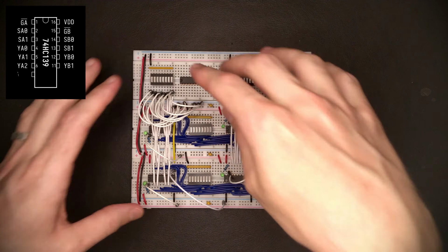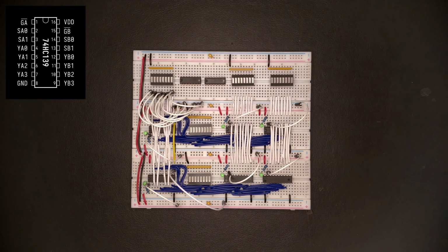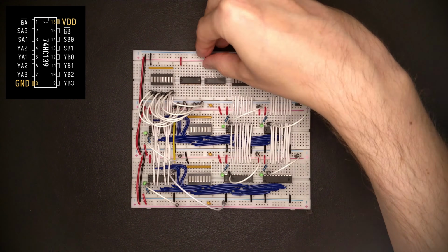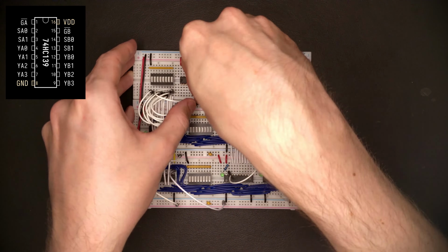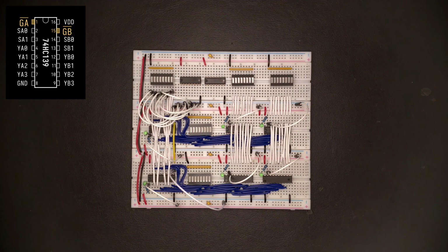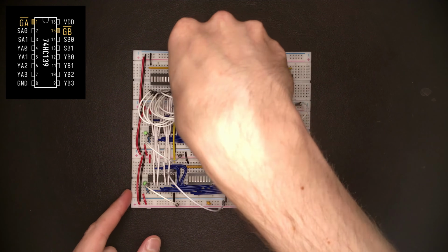Now, since we're adding active logic to the upper breadboard, let me also add a decoupling cap. And then these new chips need power and ground. Now these 139 chips, they have an enable signal, the G input, which allows us to actually say we don't want any of the outputs to be enabled. But for the time being, I think we can tie that low such that the selectors are always enabled. And then maybe we can come up with a fancy use case for them in the future.